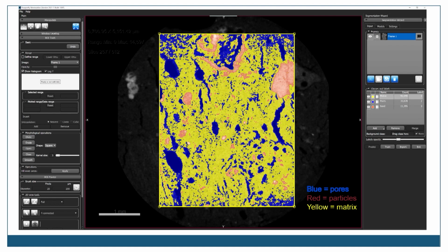And I found that a 5 by 5 millimeter field of view, which for my instrument gives 10 micron spatial resolution, works well enough. A larger field of view will miss too many of the smaller pores, but a smaller one will miss the full extent of too many of the larger pores. And given the variation within ceramic materials from archaeological sites, depending on the material, I do 2 to 5 replicates per sherd, never just one analysis.